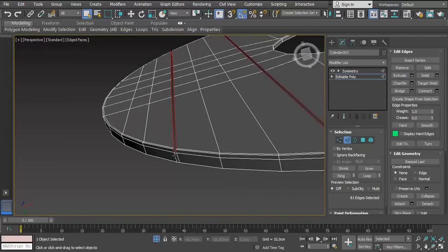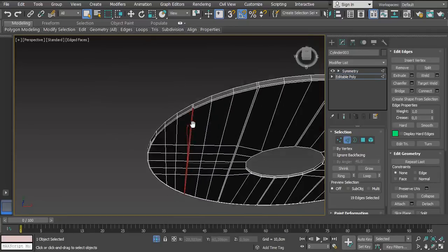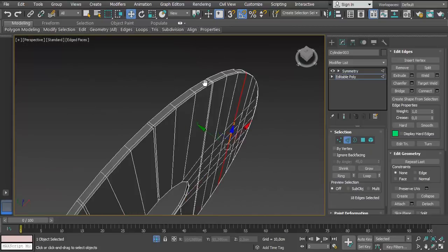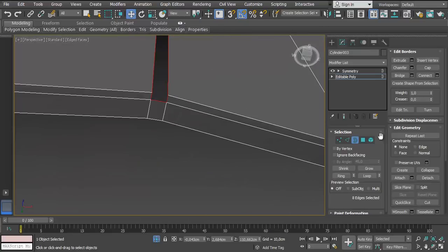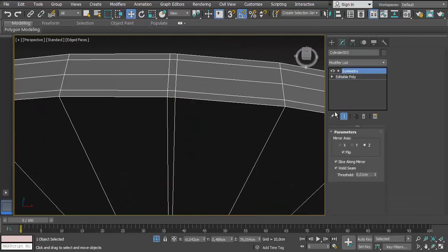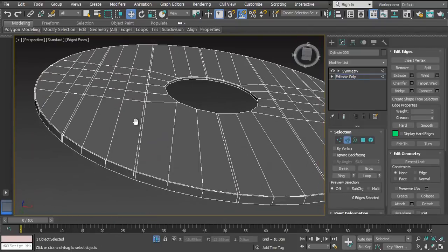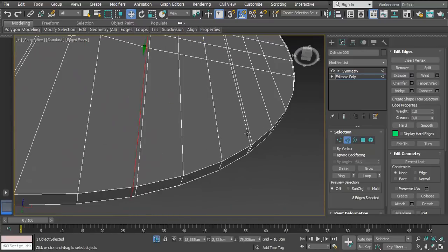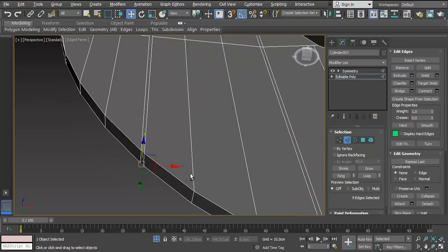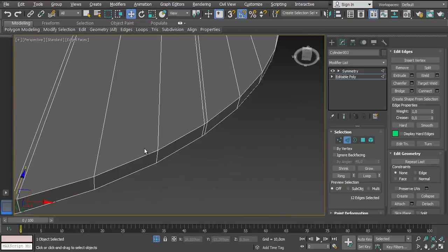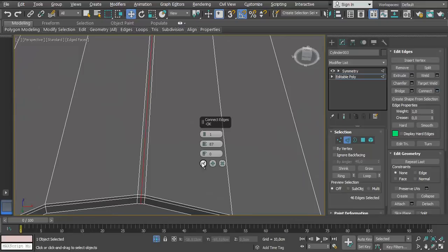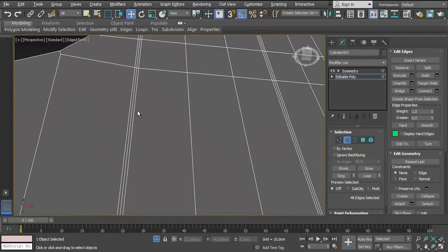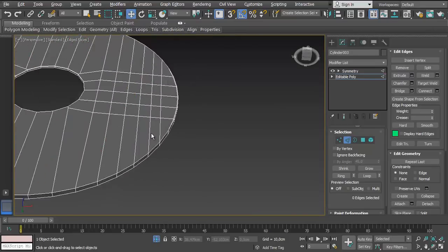Another effective way to do the conversion from the high poly to the low poly is not to convert the model to the high poly in the first place. When you start working on the high poly version, you're going to create a copy that is going to be the low poly. That means the high poly version that you create is going to be supported using support edges and stuff, and the low poly version is going to be saved in the layer explorer.